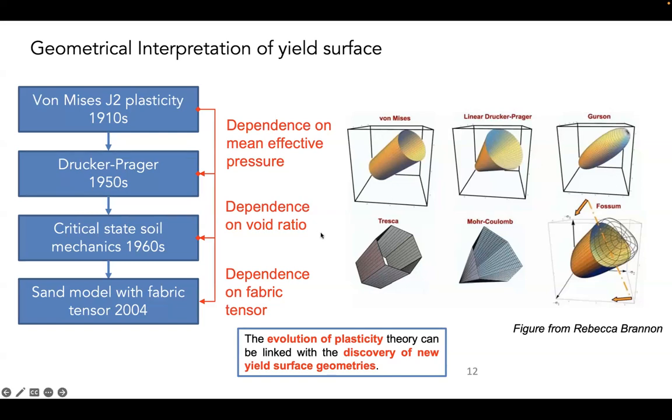And for metals, you can also see yield surfaces that are not continuous. You can see a sharp corner. This happens a lot in crystals, in metals, or in polycrystals, where plastic deformation can be triggered by discrete events such as a slip system getting activated or grain boundary movement. That also has a physical meaning, in the sense that the corner represents a very discrete event: if you are loading very close to the corner, you have two feasible slip systems or plastic flows that are equally valid.